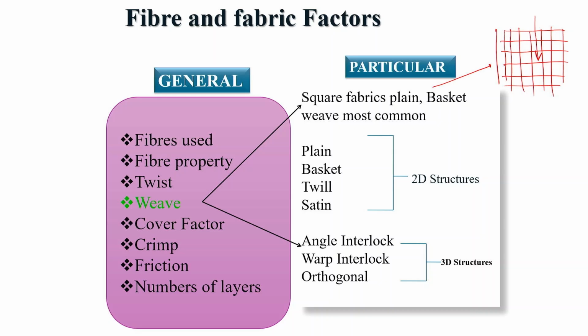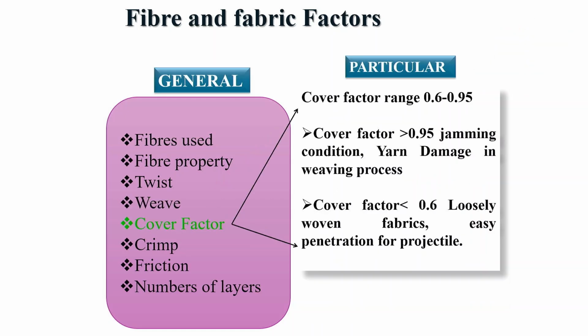Next, a very important characteristic is the cover factor. The cover factor should have a certain range; it should not be 100% jamming. The cover factor range should be around 0.6 to 0.95, that is the recommended range we have to keep. Problems would be there if the cover factor is more than 0.95.